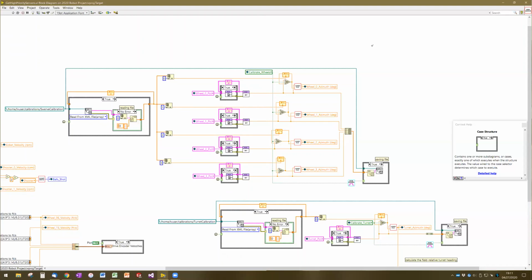Okay, so field-oriented controls, basically when you're making movements on the robot, the straightforward and driver-oriented. That's what I'm about to say. When you turn or make any movements, forward relative to you is the same. So if I push forward on the stick, it's going to go away from me. If I push back on the stick, it's going to go towards me from the driver. And then field-oriented would be if I turn 90 degrees and then go forward, I'm going to go forward in the direction I just turned 90 degrees to. If that makes sense. So the definitions are correct, although they are reversed.